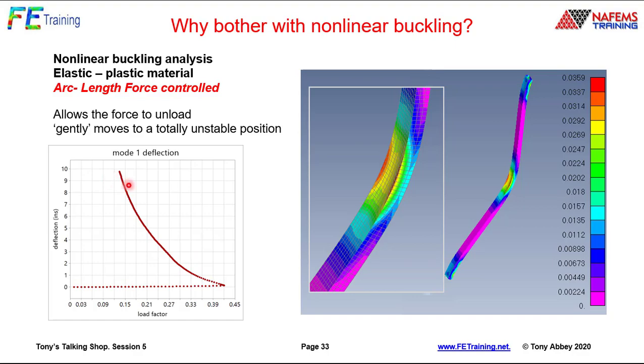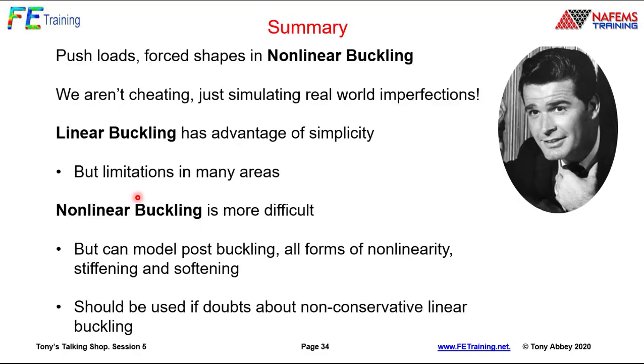We would do this more probably if the next configuration was a stable configuration. So we buckle, it then transitions to another stable configuration. We really want to understand how it does that, so we can chase post-buckling a little more carefully, rather than something like our beam is just going to fail catastrophically.